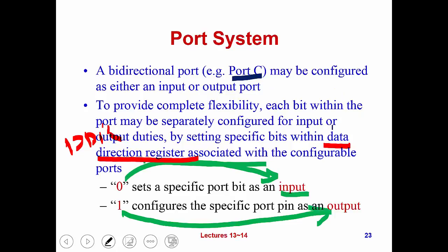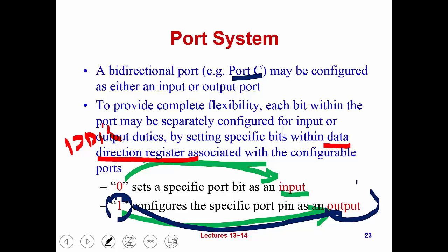11111111, because 1 corresponds to output. We hope to change our port C, all 8 pins, to be output data. In this case, you have to make its corresponding data register bits all ones.